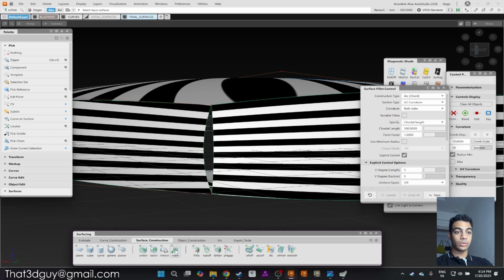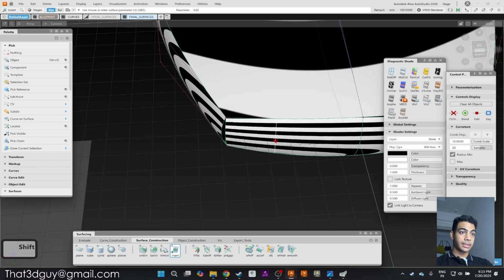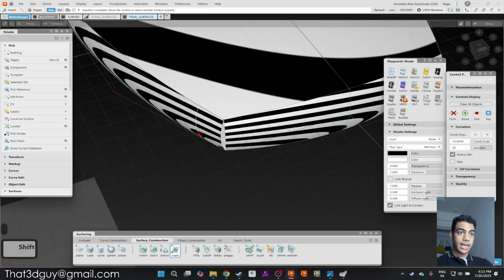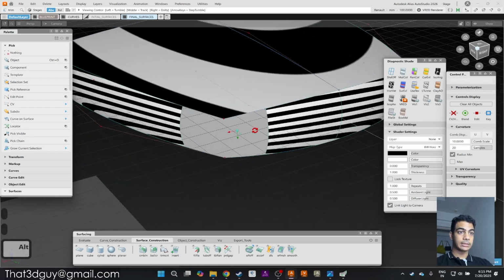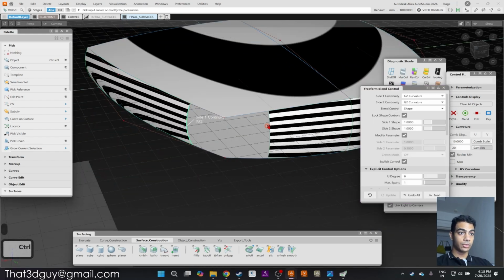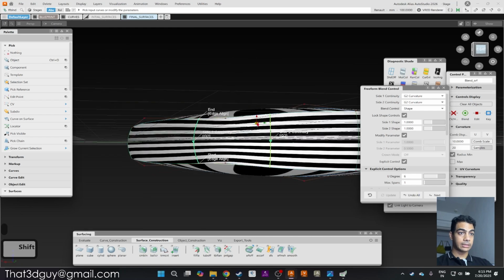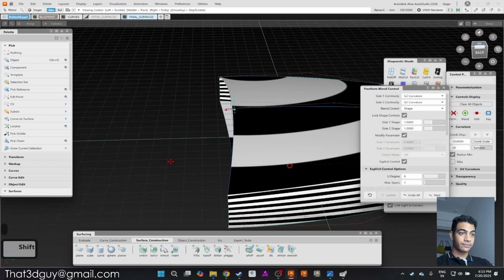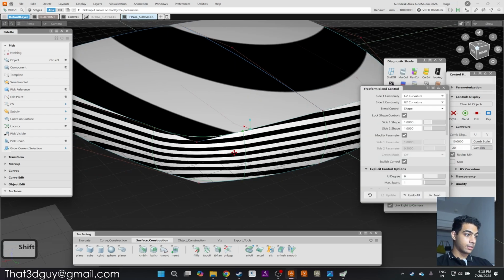But what I would try to do is I could use insert. So there is an insert edge, basically takes an edge from the true edge and we can slide it back all the way till here maybe, and all the way back here, and then we can trim these. So if we trim these, it's gonna look something like this. And now when we freeform blend it, it should do the task. Let's see, G2 continuity, edge align on both sides, and something like this. Perfect. So we do have something which now makes more sense and a bit more interesting, right?